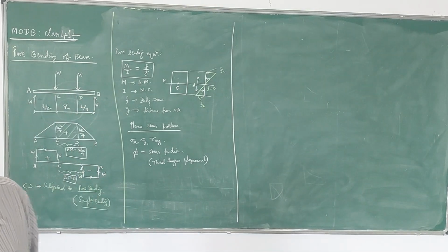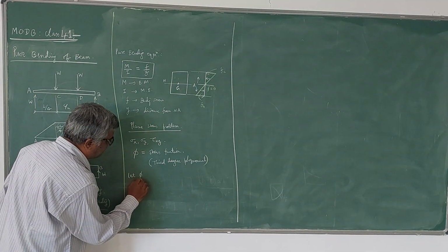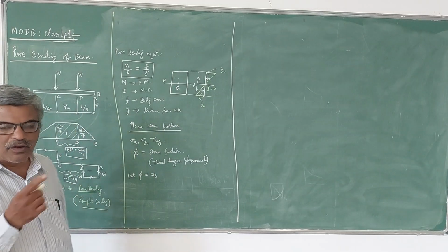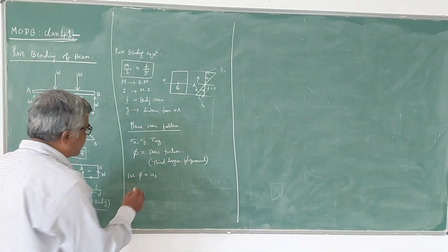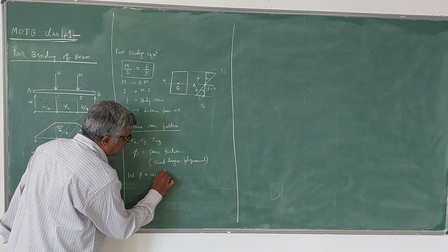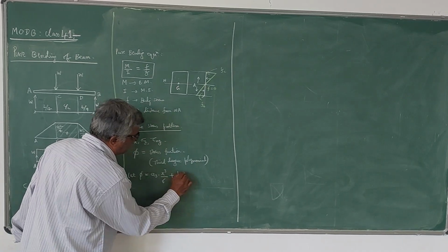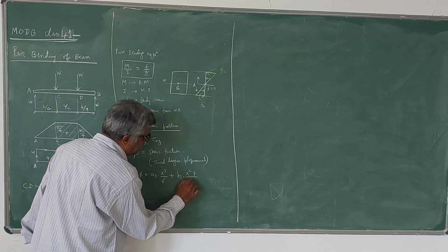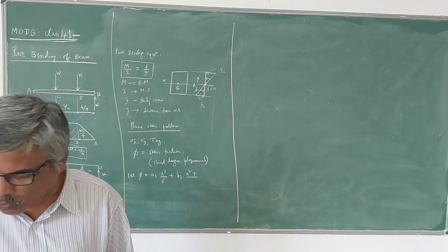The third degree polynomial will be assumed like this: phi is equal to A3, because I am taking third degree, the coefficient subscripts I am going to take as 3, A3 into x cube by 6. So this is a third degree polynomial, plus B3 into x square y divided by 2, reducing the power of x by one and introducing y.